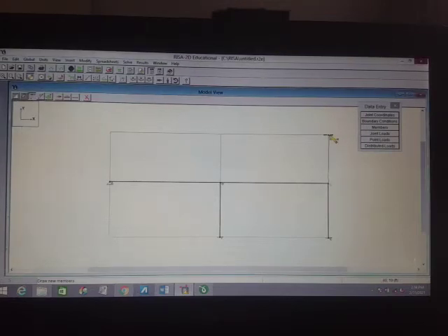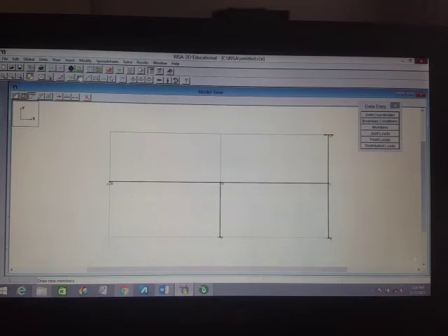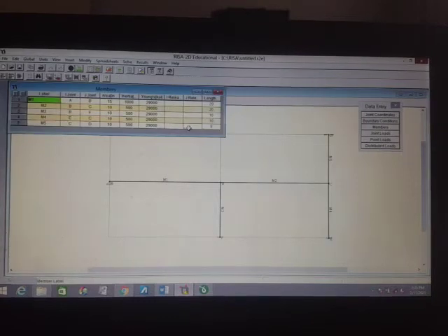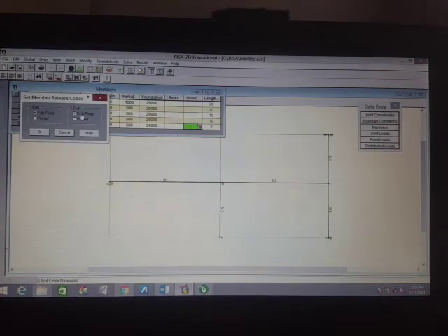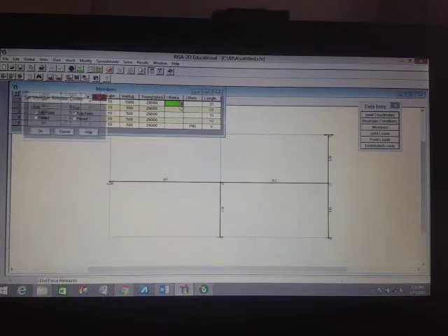Okay, I think we'll try this pin at this point. Okay, we'll check. We can edit if we want. So for our member 5, you can also view or turn on the labels. Let's say this is our first and this one is the last. So we'll edit. Let's say this is pin. Okay, pin. And for member 1, for this pin support or pin boundary condition, now we'll check if this is pin. Okay, so the B is pin.